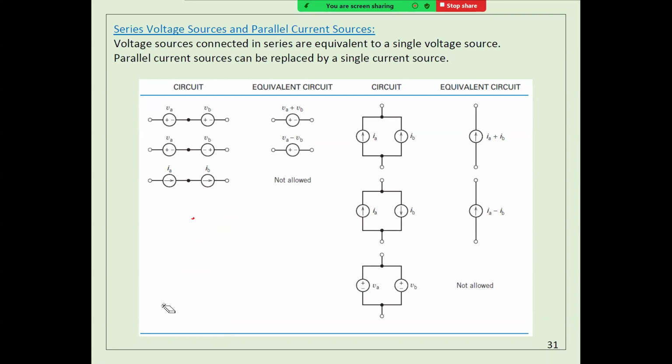So if you have two batteries, these two batteries are connected in series this way. If you have here voltage X, for example, what should be the voltage here? It has to be X plus VB, right? And what should be the voltage here? It has to be X plus VB plus VA, right? Because every time you move from the smaller to the greater, you add, right?